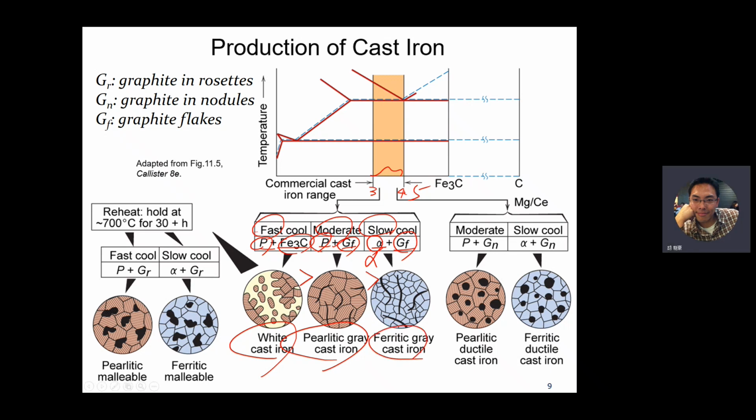Okay, and for the higher carbon content, close to 4.5 weight percent of carbon, with the moderate cooling rate, its microstructure is pearlite with nodular graphite.